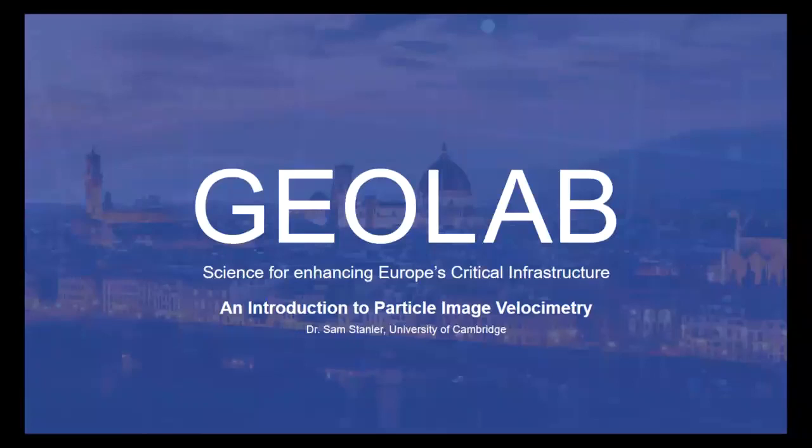Thank you for your presentation. Very nice. Do you have any experience with analyzing liquefaction problems with PIV, obviously? Personally, no. As in, I've not personally run any of these analyses. I have had interactions with a number of people, particularly at Cambridge, who were working on liquefaction problems. So Orestes Adamidis was one. There was another couple of students in the last few years working on those problems. In essence, as long as you've got good quality images with the right resolution, the problem is no different. To the PIV algorithm, you've just got arrays of image intensities. So in principle, as long as you've got good quality images, it's the same issue. The challenge is that I think in a dynamic environment where you've got typically more modest camera resolutions in order to get very high frame rates, getting the right image quality is more of a challenge.